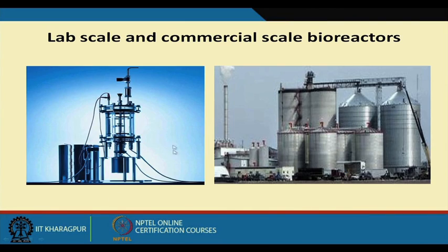Particularly we know that sulfite, if present in the liquid, gives some kind of corrosive property, and so do some acidic media. So epoxy is a very good coating material, which can give protection to the mild steel, so that the liquid will not come in direct contact with the metal surface. This is largely used by the industry, and it is very useful.